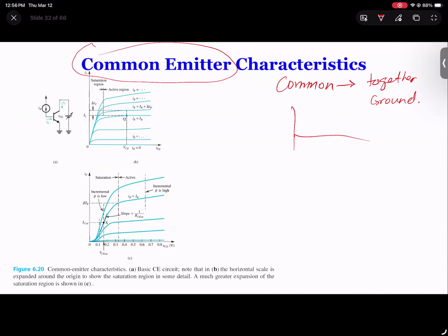Like if you have a waveform like this, you have DC and AC. Remember, there's one important thing from the very first lecture, when I went through circuits: we have superposition. So when you do superposition, you open the current source, you ground, you short the voltage source.